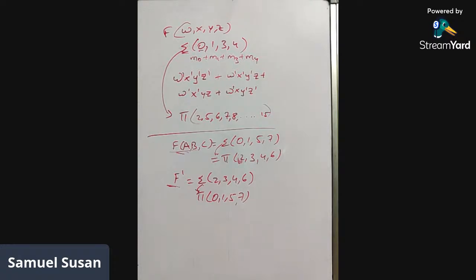Fourth unit, after the magnitude comparator, the very important concepts are decoders and multiplexers. They are very much important. For decoders, there are different sizes, 2 by 4, 3 by 8, etc. Sometimes you are asked to implement a 3 by 8 decoder using 2 by 4 decoders, or a multiplexer from a smaller size to a larger size. That is, implement a 4 by 1 multiplexer using 2 by 1, or a 16 by 1 multiplexer using 4 by 1. Such questions are repeated so frequently.